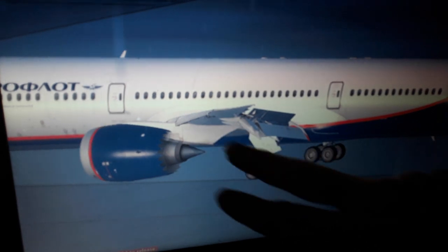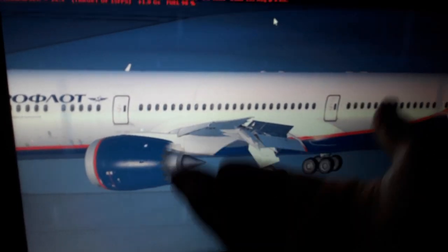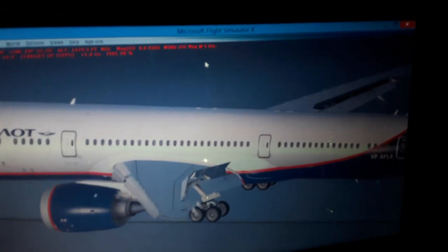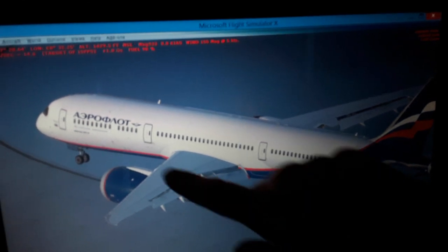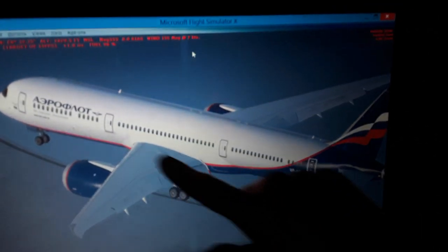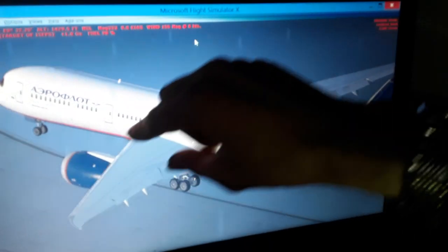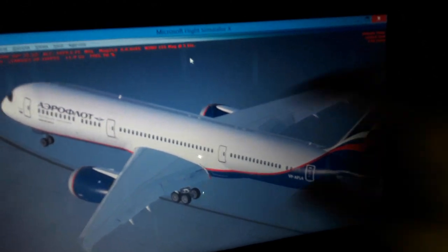So we have higher pressure below the wings, which pushes the aircraft with the wings up into the air. Also, the top surface of the wings, again using fluid mechanics, is more curved, so the airflow is moving much faster above the wings, which sucks the aircraft and wings up into the air. It creates lower pressure.